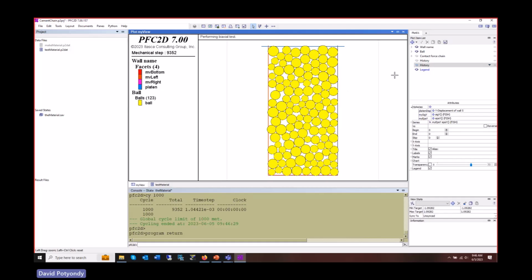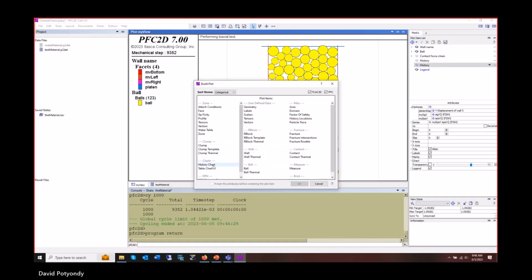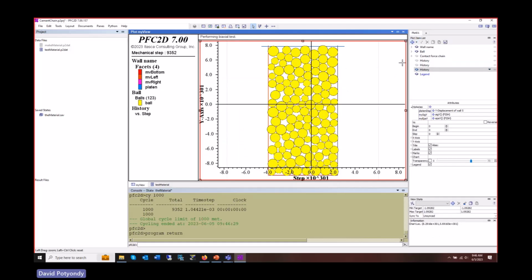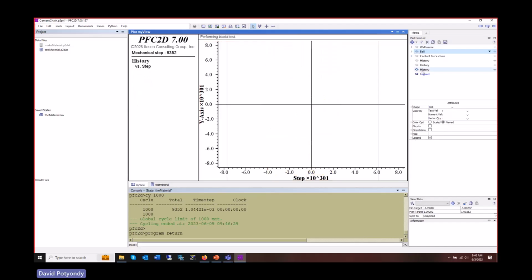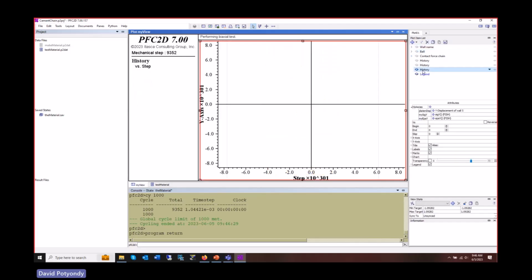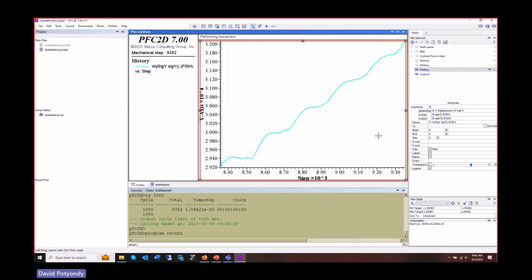So now let's make another history. What do I want to plot here? I want to plot sigma y versus epsilon y. So I click here, sigma y. There's sigma y. And then it says VS here. So the VS is the thing called my eps y. My eps y. Boom.